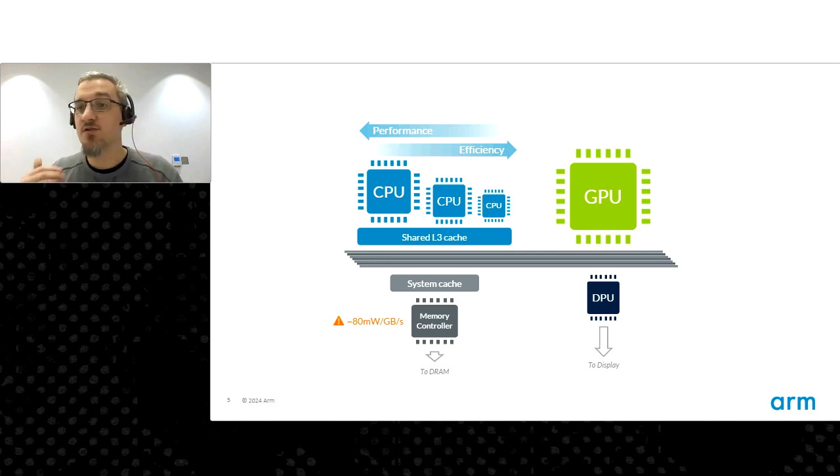So if a workload is too complicated, too many layers, too much color conversion, too much rotation, you may find the OS compositor simplifies the workload using the GPU and then passes that composited image over to the display processor. So if you can, again, through Vulkan especially, you don't want to give the DPU things that might fall back. So just one to watch out for, but we won't talk about that one much today.